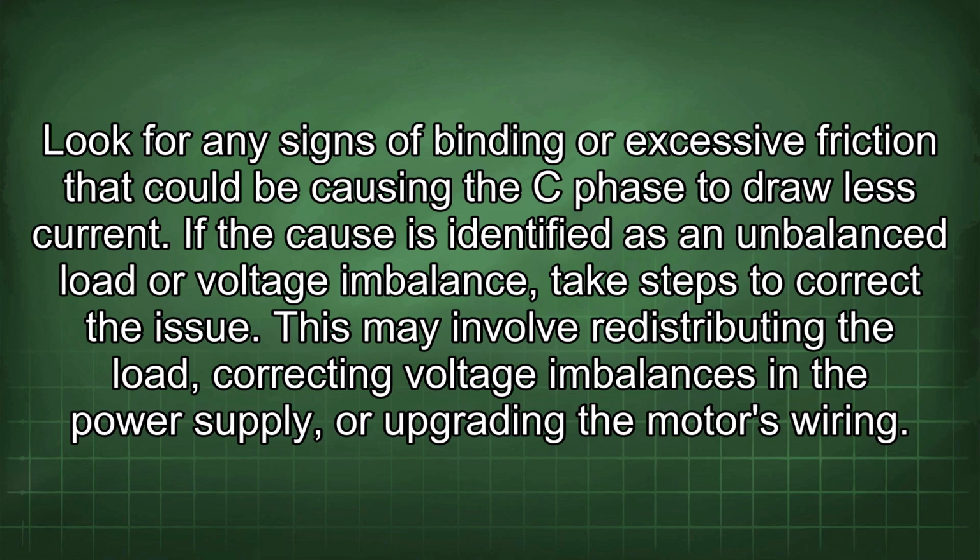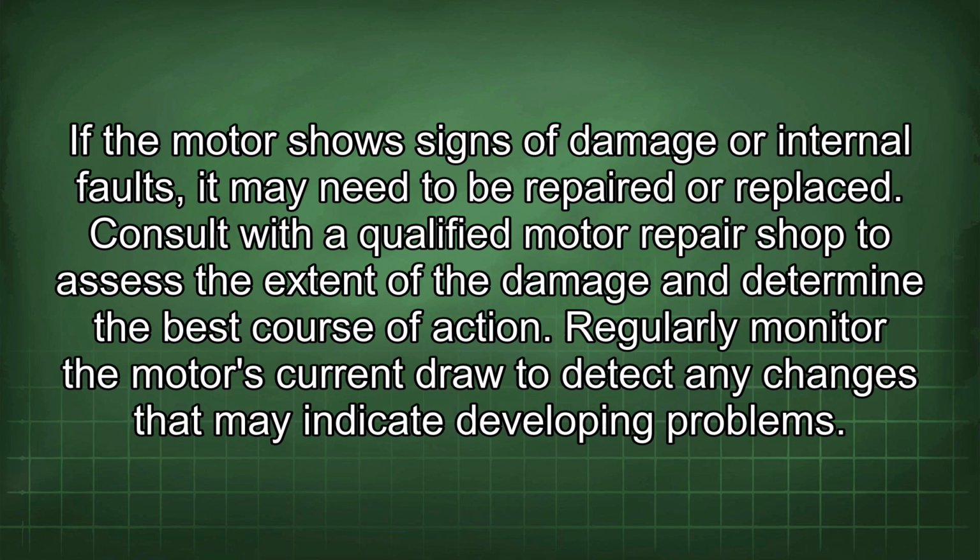If the cause is identified as an unbalanced load or voltage imbalance, take steps to correct the issue. This may involve redistributing the load, correcting voltage imbalances in the power supply, or upgrading the motor's wiring. If the motor shows signs of damage or internal faults, it may need to be repaired or replaced. Consult with a qualified motor repair shop to assess the extent of the damage and determine the best course of action.